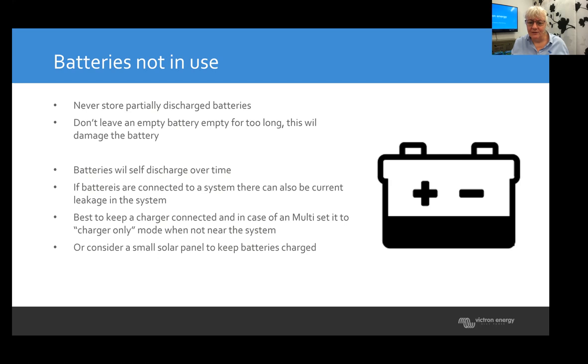Nearly all our chargers have what we call storage mode. So after the 3 charge cycles, it goes into the 4th cycle, which is storage or reduced float. That's especially made for keeping the battery charged and combating self-discharge. Every week it goes through a little cycle where it stirs everything up.